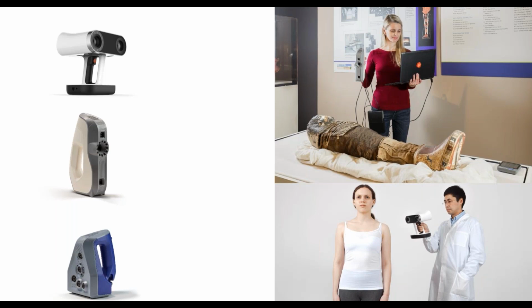Handhelds typically lose some accuracy over distance. So if you're shopping for these, you're going to see two accuracy ratings: a given accuracy on any given measurement, and then accuracy over distance. A lot of times there are additional systems like laser trackers or photogrammetry systems that can augment these type of systems to hold better accuracy on really big objects.